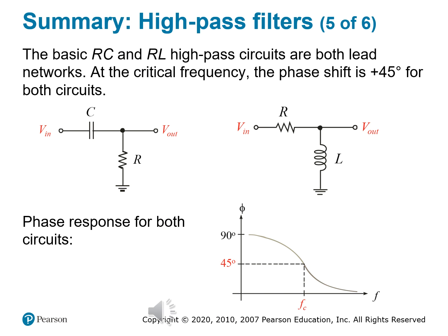At low frequencies, the phase shift is close to 0 degrees, so that's almost no shift. But at high frequencies, the phase shift approaches plus 90 degrees, and that's like a full quarter wave lead. But again, there's the sweet spot, that critical frequency or cutoff frequency F sub C, where the phase shift is plus 45 degrees.